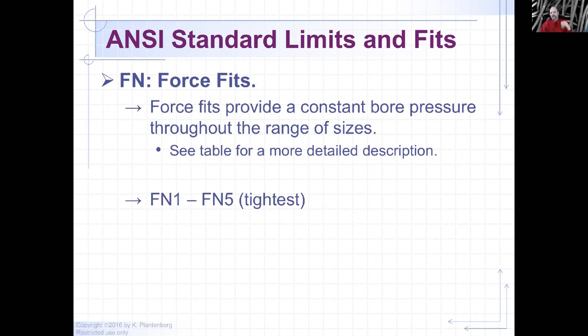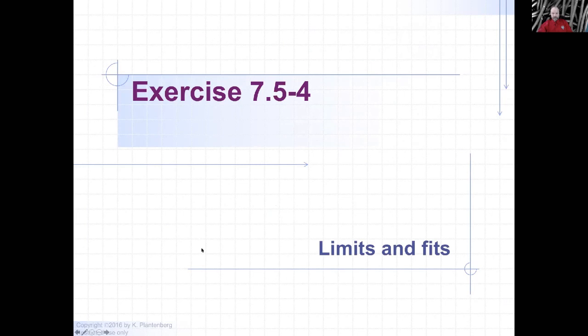A lot of times if you're doing a force fit, or putting parts together at yield, they'll heat up one part, say the part with the hole in it, which makes the hole bigger. Then they put the shaft in, and when the heated part cools down, the hole gets smaller, and it becomes a force fit, a really tight fit. Okay.